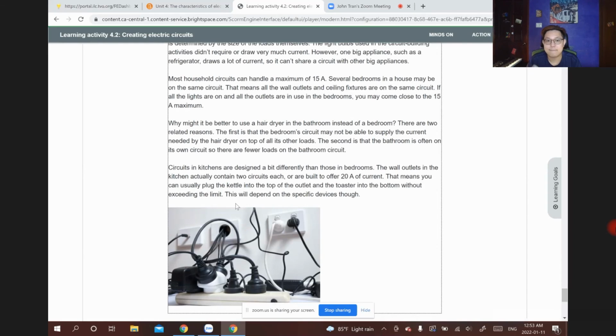Yeah, turns off. Because why? The electric oven, water kettle, and microwave oven are all consuming a lot of electricity. And when you exceed a certain load, the CB or circuit breaker has to turn off to prevent burning, to prevent accidents.